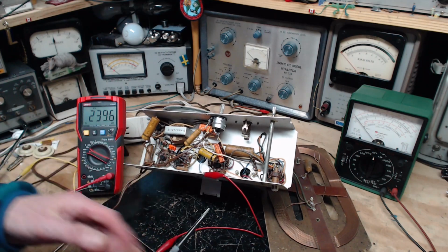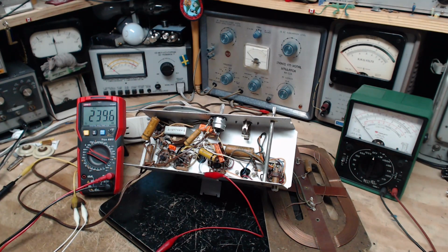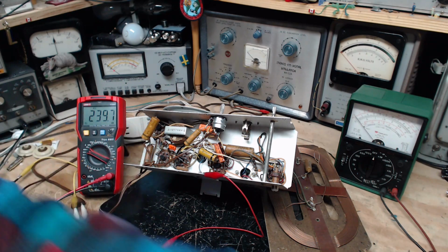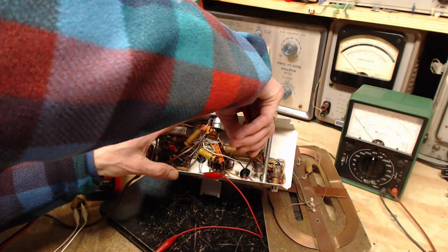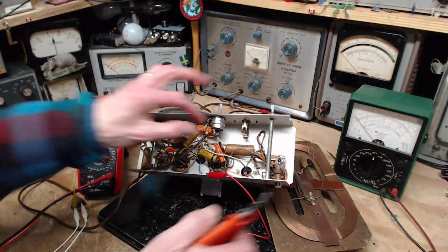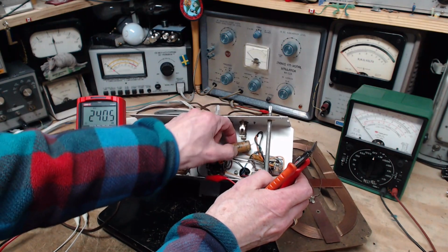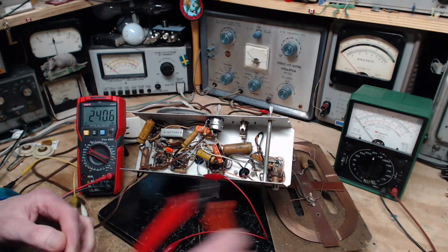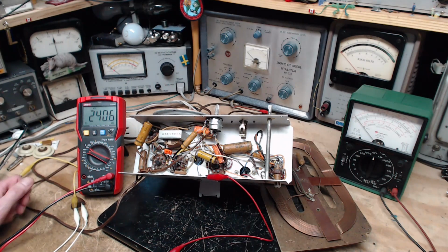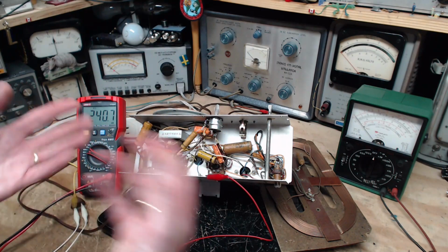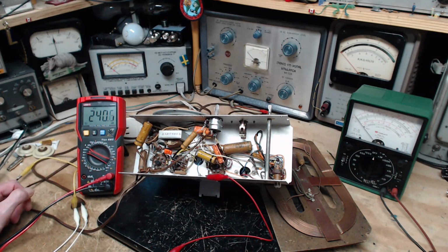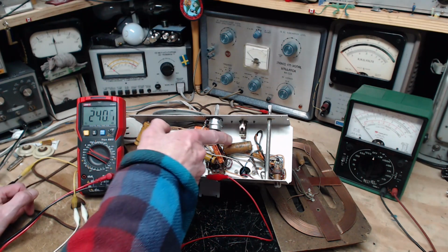So this resistor has nothing to do with... Where's the mystery resistor? Let's cut the capacitor right out, because I'm going to replace it anyway. We'll just cut it here. Okay. Somewhere there's a resistor in here I can't find. Underneath something, hidden away. It's got to be in here somewhere. Okay, but you can see we cut out the capacitor, made no difference. So the amount of current leaking to the chassis is really controlled by that resistor and this capacitor. If it was adding to it, it was adding a tiny, tiny amount of no consequence. So does that mean this capacitor is safe to leave in here?